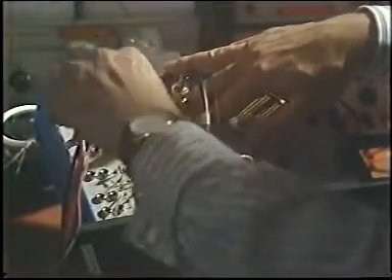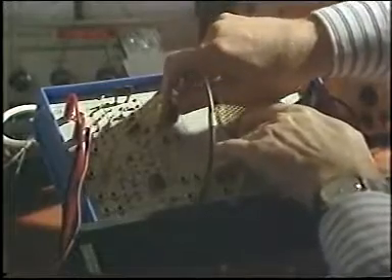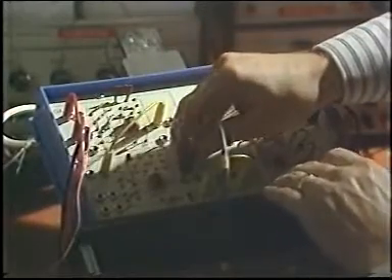So, Mike? Yes, well, I've patched up a low-pass filter on the analog module here. You'll recognize your home kit module. And let's have a look at the effect of a low-pass filter. Take the signal into the input of the filter and transfer the probe to the output of the filter.